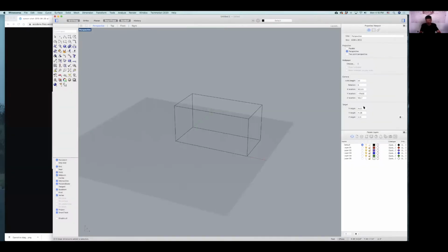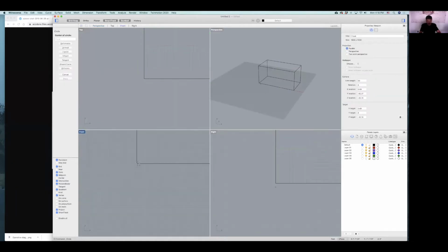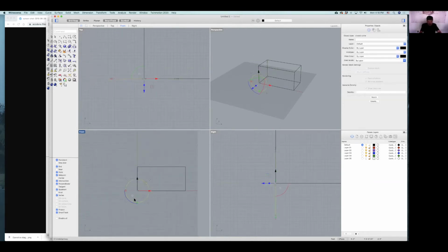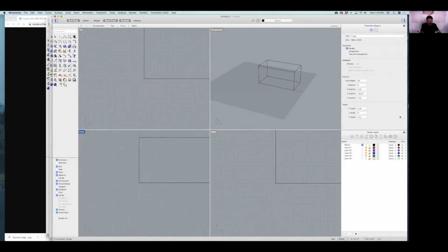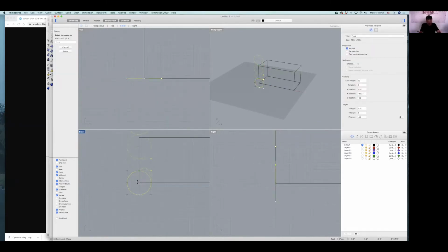First, we are going to get to our default layer, go to the front view, and draw a bunch of circles. So on this view, I am going to draw a circle, copy this circle a couple of times. I will draw my circle and then copy it at quadrant, copy it 3 times, and take those 3 circles, move by typing M, move tool, move to here.